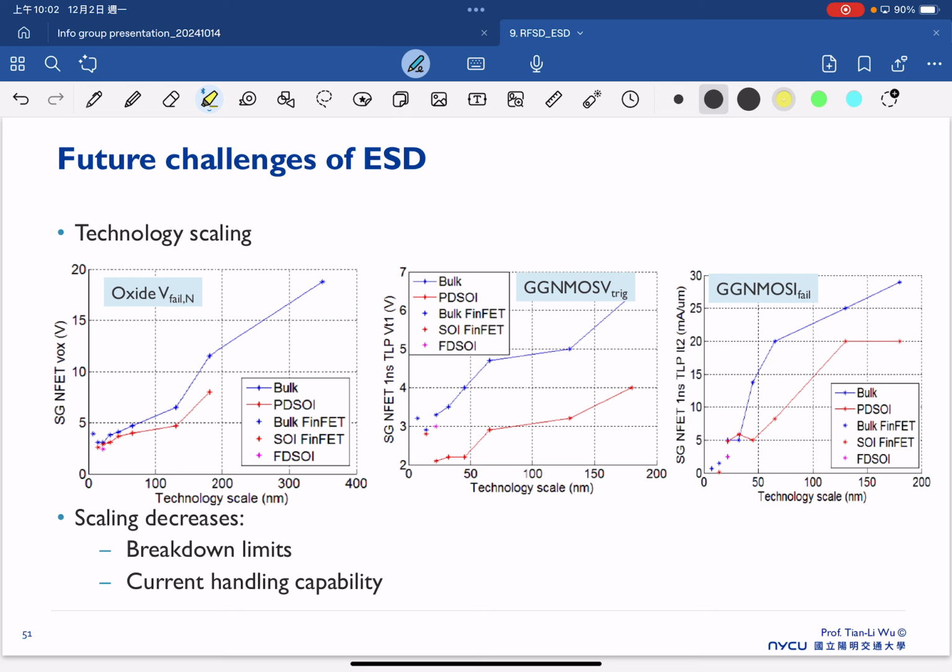And once you use a high-K, we suffer huge defects in the high-K material. And for the FinFET, we now have not only planar BTI but also the vertical channel, where we also suffer BTI, especially since the vertical plane has a different crystal orientation compared to planar, so that will cause a different trapping mechanism.